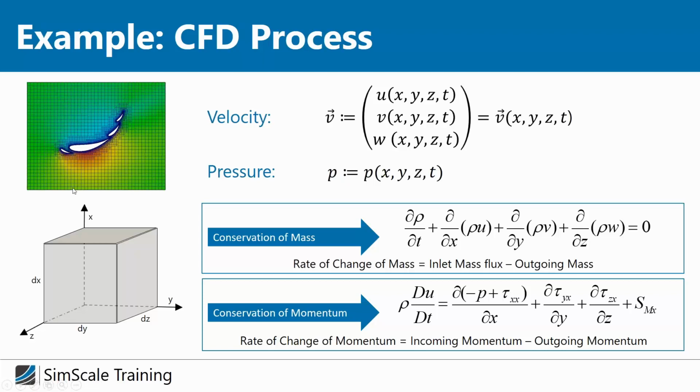So instead, we divide our wing structure into small shapes as elements, and then we can look for a numerical solution for these simplified shapes. And then instead of computing a function for the values of pressure and velocity around the wing, we just calculate approximate values for every center of these cells.